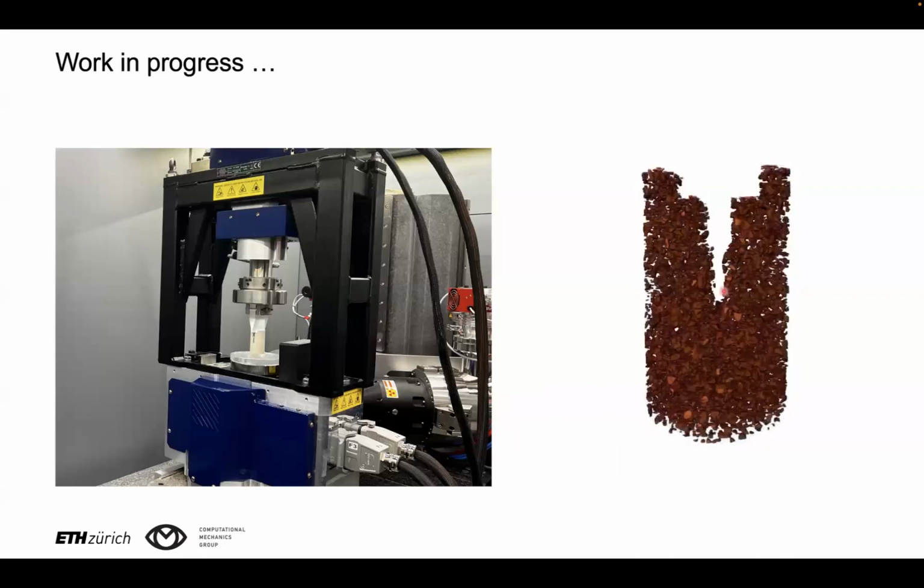We're using different geometries of specimens at the moment. The objective is to find stable test setups to observe stable cracking, so to be able to track the propagation of cracks during loading. I hope that we will publish soon the first results of in situ testing compared with phase field modeling through the mesoscale setup that I've been describing.